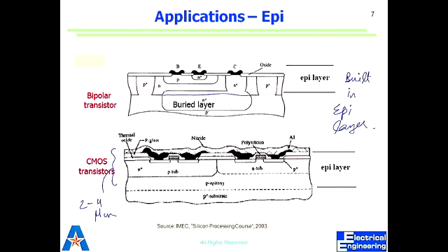So if you heavily dope it, right. Okay. When we say epi, we are talking about two materials. The resistance between them is minimal because it's the same material. It's just one is heavily doped, the other is lightly doped. Instead, if you have another material, the interface will become a resistive element in there. So we are talking less resistance when you are making a material on top of another material. Since it's following the crystalline structure, there is essentially very little resistance between the two materials.